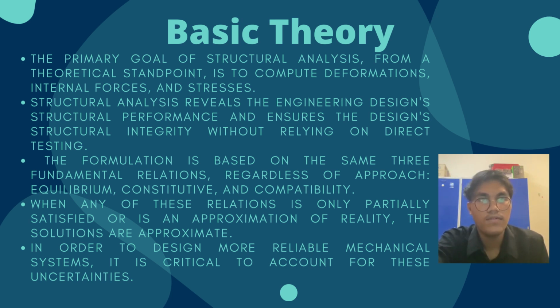Because of the need for strength and efficiency, the geometry of these load-bearing structural components is usually complicated. The structural engineer must determine structural loads, geometry, support conditions, and material properties in order to perform an accurate analysis. Support reactions, stresses, and displacements are common outcomes of his or her analysis. After that, the data is compared to criteria that indicate failure conditions. Dynamic response, stability, and non-linear behavior are all things that advanced structural analysis can look into.